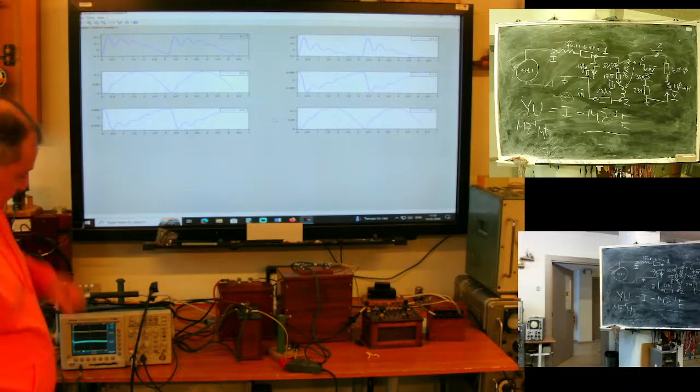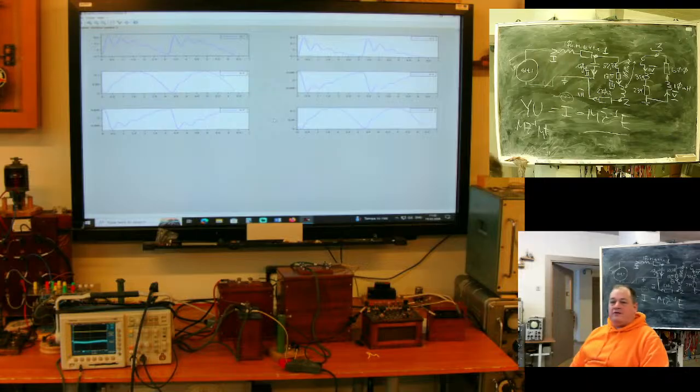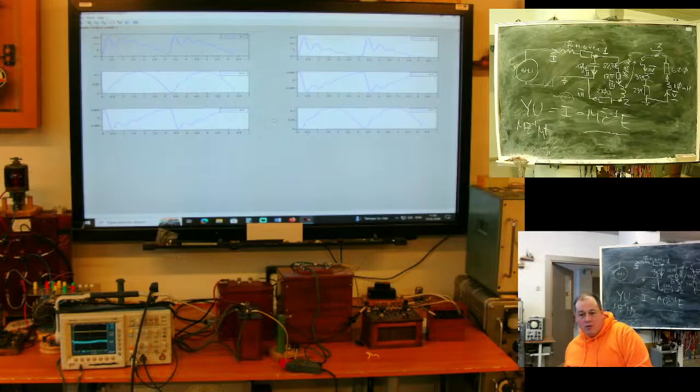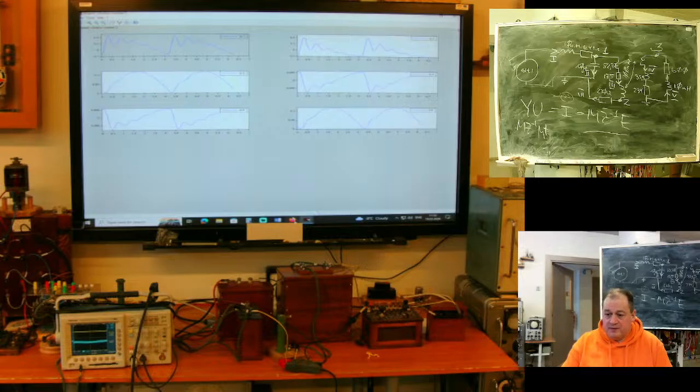Okay, network. I can switch off. Here, with the help of discrete time Fourier transform, I can solve very complex network. What is the process? Create signal table, perform discrete time Fourier transform, solve multiple ideal networks, perform Fourier synthesis, and you got all values you may need.